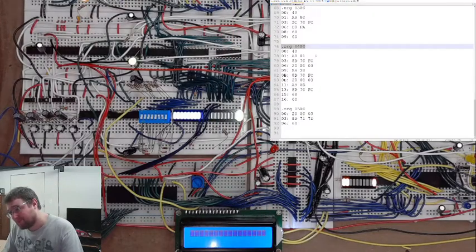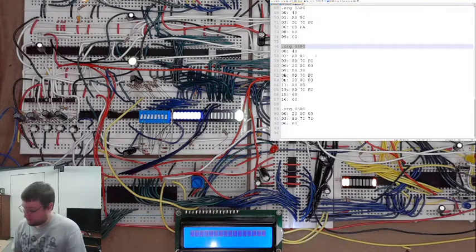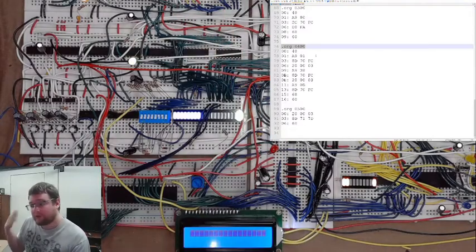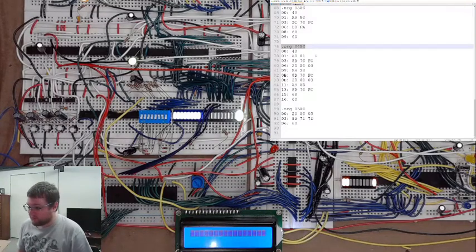It's more than it needs. You could probably get away with 1 or 10 nanofarads, which is definitely what you would put on a printed circuit board. But you'd also have more power availability on a printed circuit board because you'd have your ground fill plane and your positive fill plane. And so there would be no resistance there for the electrons to get to where they need to go.